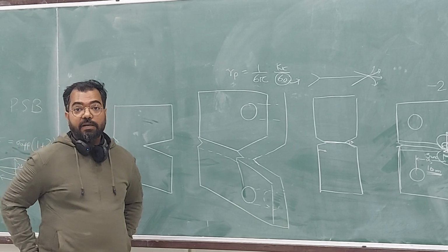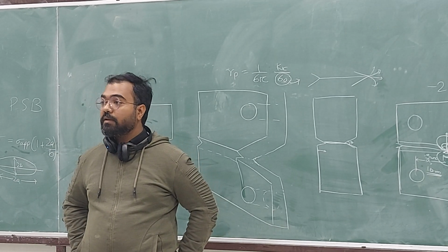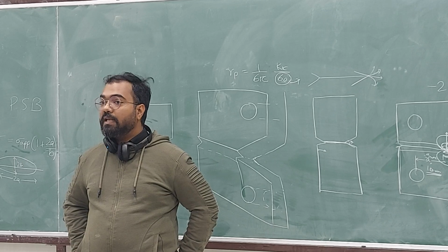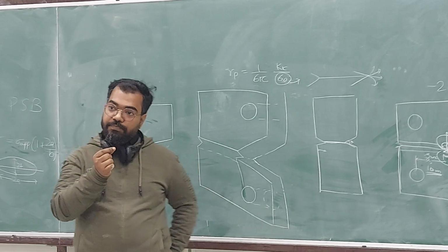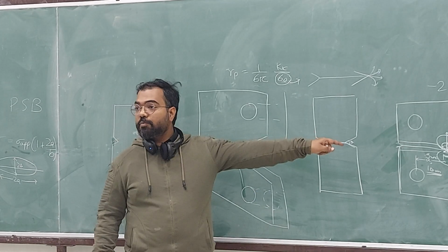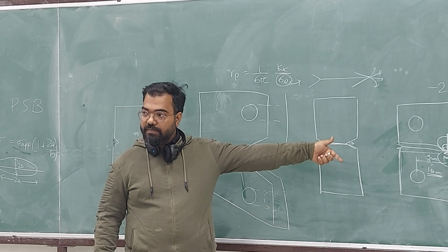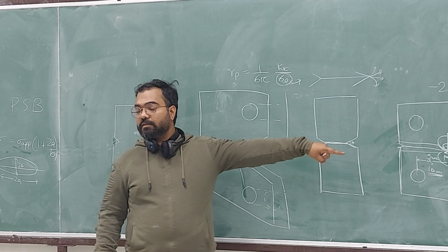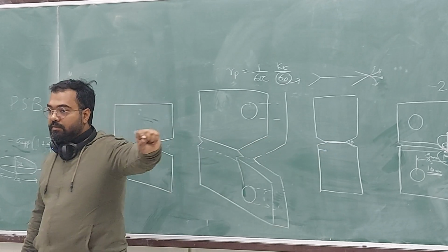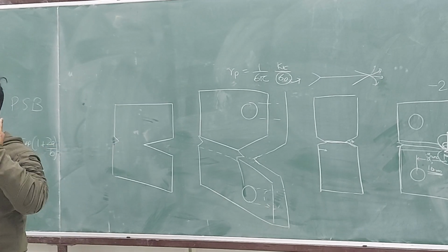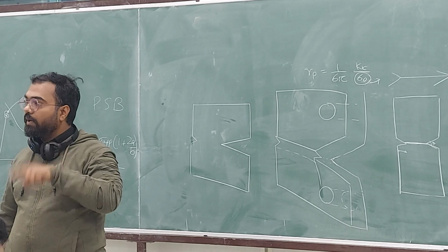The defects which really come in pressure vessels and aircraft are probably because a bird or debris will hit it, and that will be a marginal scratch, a very small scratch, and that scratch will have an a by W of 0.1 or less than that. That's a very shallow crack. Even then we are doing it in an extreme region of 0.5 a by W, because first it will ensure the conservative design criteria. So the worst condition, then you will say why not 0.6?